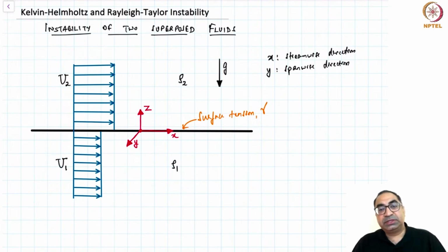And notice that at the interface where the two streams meet, there is a discontinuity in the velocity. This is allowed because we are solving this problem for an inviscid flow. If there was viscosity, then the initial condition of a discontinuity would not be correct, and we will have to smoothen the velocity profile. But we'll keep the analysis for an inviscid flow because it's analytically tractable.